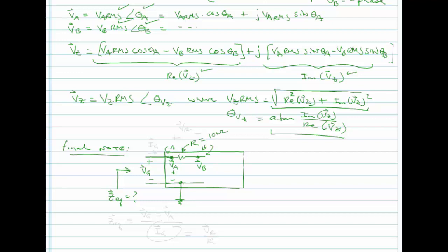So what I'm really trying to do is calculate the equivalent impedance Z. What I need to know there is the voltage VG, which presumably is equal to VA. It's the same thing. And then I need to know the current going in, so I'll call this IG. IG can simply be computed by looking at the voltage across that resistance, VR. I can calculate IG by doing VR over the resistance. And how do I get VR? Well, we just calculated it. That was our VZ for the general case.